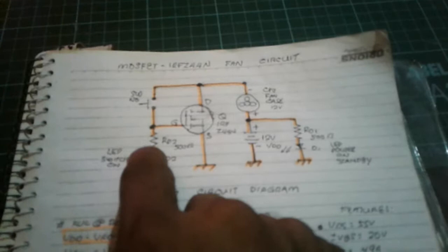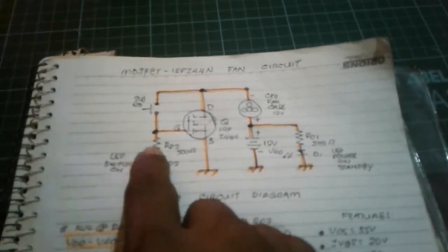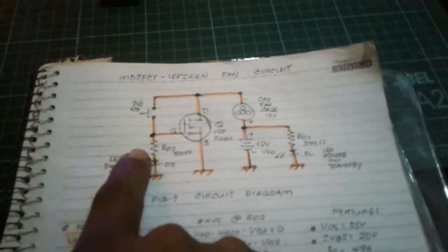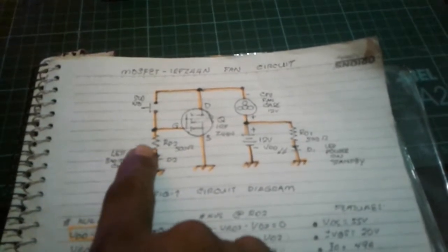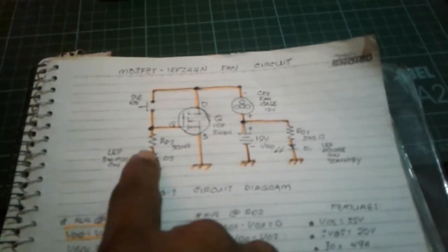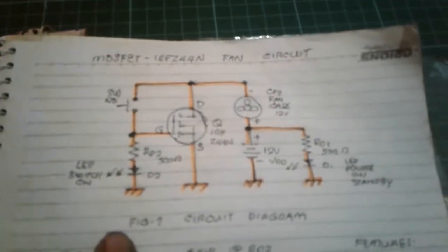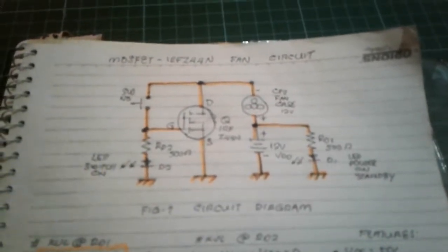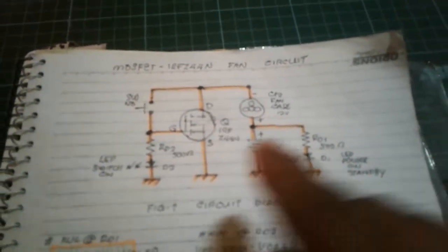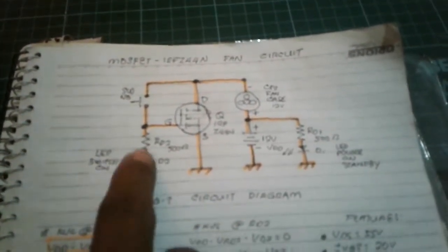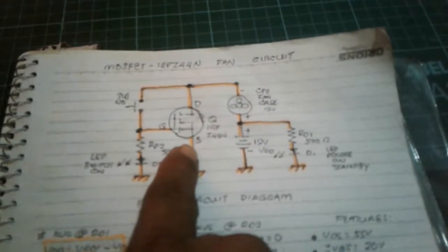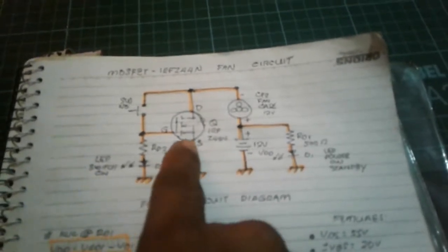So you need this resistor, pull down resistor to turn on the power. At least a resistor here, any value, could be 50 ohms up to 1 mega ohms, or sometimes YouTubers use 10 kilo ohms. 1 kilo ohms also okay, as long as there is a resistor here to prevent the capacitance to develop in the Mosfet.